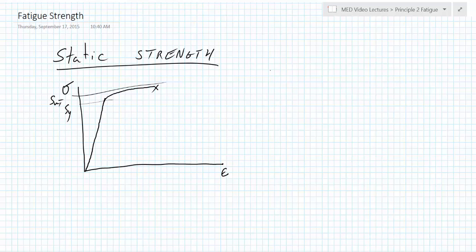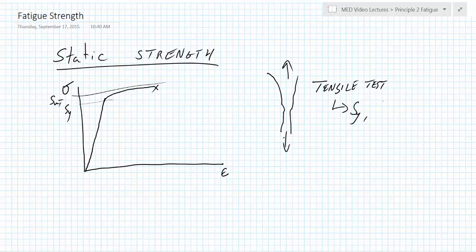So we put the machine in a test specimen, usually looked like a notched test specimen, and we pull on it and get these numbers. Now we use the tensile test to come up with our yield strength and our ultimate strength in tension. And we can do some assumptions, assuming that compression or bending stress likely gets us the same results. And it turns out those assumptions are just fine.